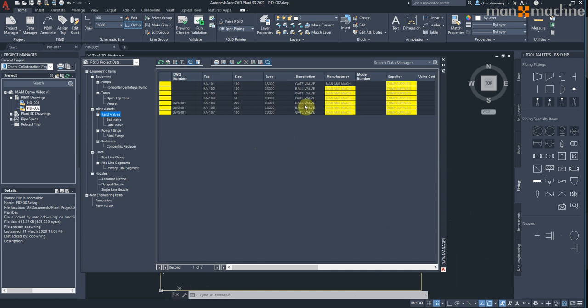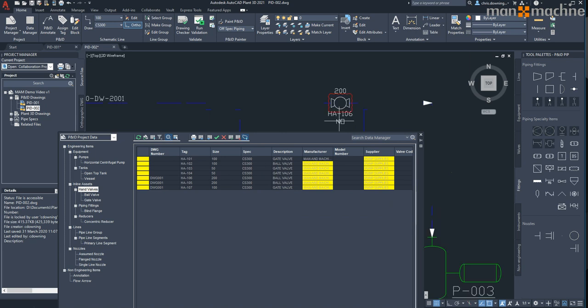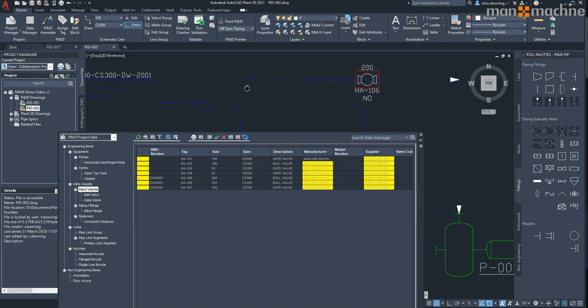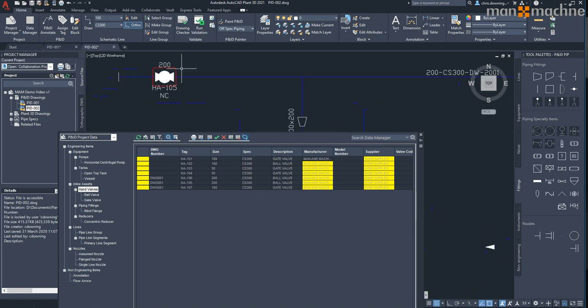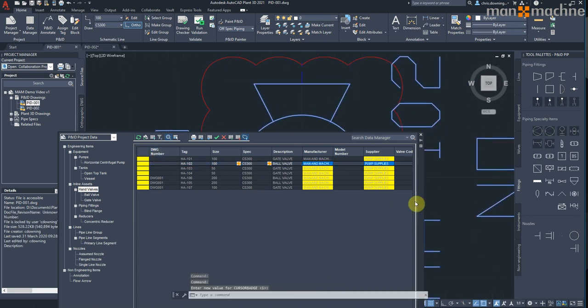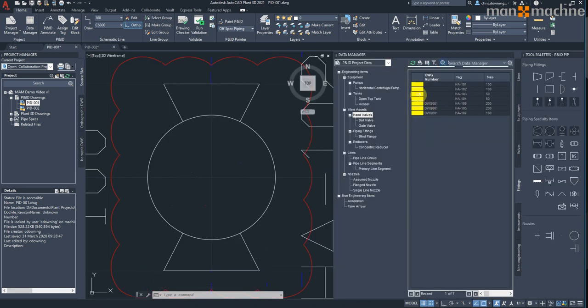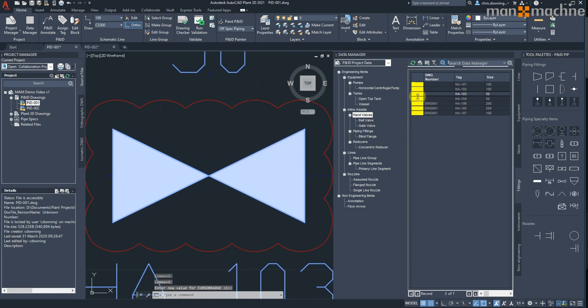And you can see that all the changes have been highlighted in yellow. And we can go through and actually view the changes on the P&ID as well. They get clouded, like so, with a nice red cloud, so you can see what's changed. And you can go through, clicking on each one. It zooms straight away to the one that's affected and shows you the cloud, like so.